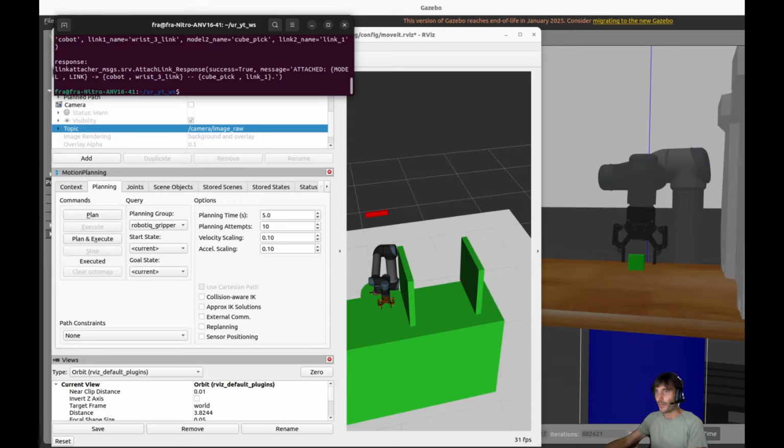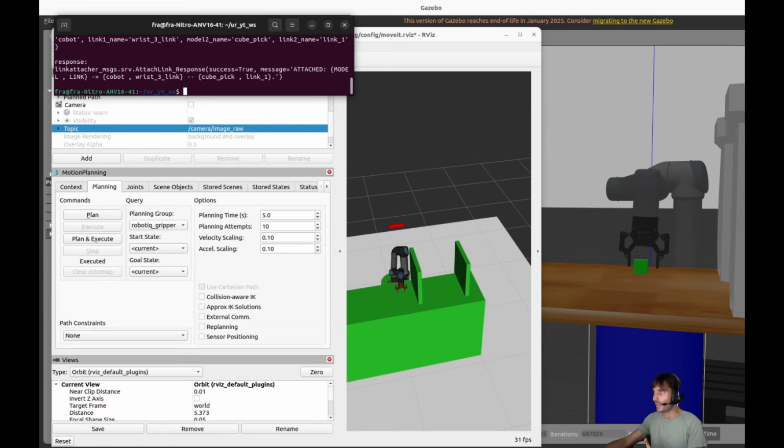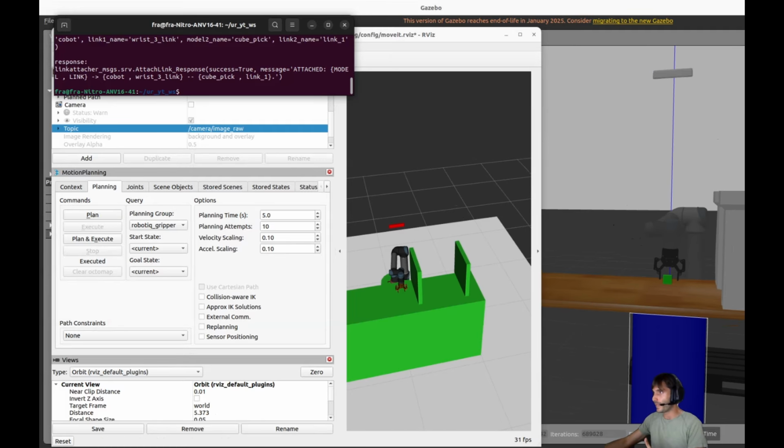Okay, so now let's go for making a picking. Let's ask the robot to go to this position inside the bin. Theoretically, MoveIt is gonna see that there's gonna be a collision object, in particular this wall that we have hard coded, and let's see the kind of motion planning that it is gonna do based on that.